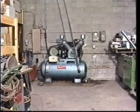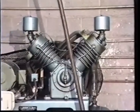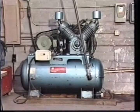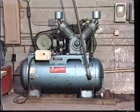Drying and cleaning compressed air for use in manufacturing, fabrication, and research applications is critical to the success of the operation. Let's briefly examine the problems that can be caused by compressed air. The air discharged from a compressor is usually hot. Cooling it causes condensate, which can contain particulate material, oil, and other contaminants.